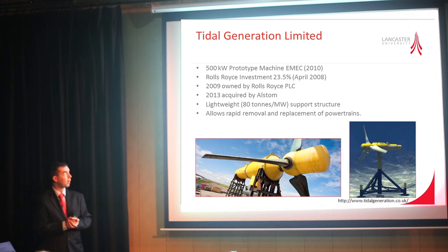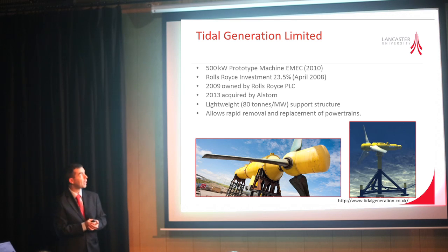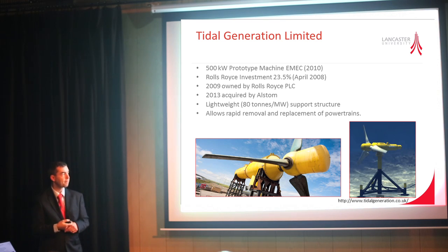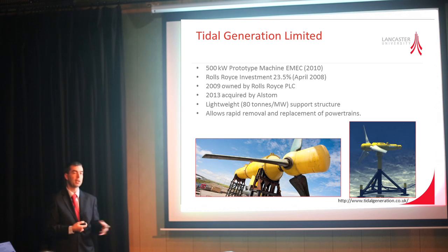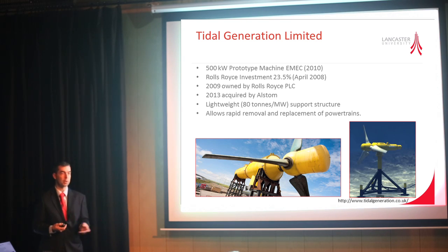Tidal Generation Limited, acquired by Rolls-Royce, now been acquired by Alstom, are probably the second place. Slightly different in terms of the concept of how the device works. Still a horizontal axis in terms of the device, but the idea here is that the whole nacelle arrangement floats. In that respect, on the seabed, you put your foundation structure in place. You then float down using an underwater vehicle to secure it in place. It then produces energy. For any maintenance that's required, you simply release the nacelle from the foundation. It floats up to the surface again. You tow it back to the harbour where you do your maintenance before you tow it back again.